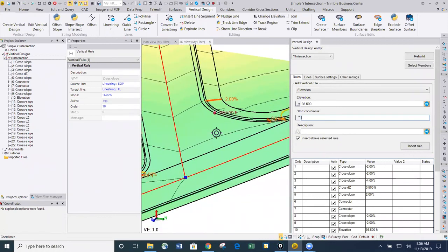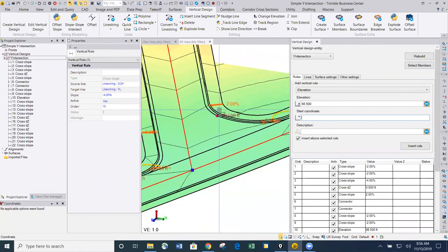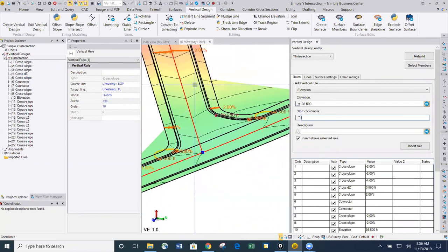And depending on where you place it in the list, this is the key, you should probably do that when you're doing the pavement before you waste time doing all the sidewalks and the curb and gutter sections. And make sure you get all the drainage and everything right for the pavement before you start adding all the other elements in. Okay, does that answer the question?